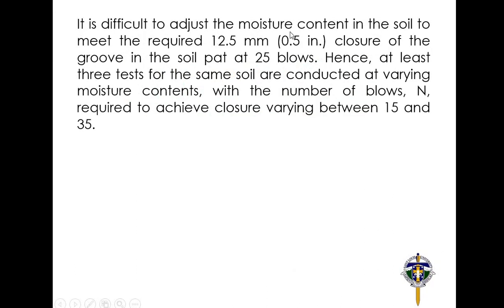It is difficult to adjust the moisture content in the soil to meet the required 12.5 millimeter closure of the groove in the soil paste at 25 blows. Hence, at least 3 tests for the same soil are conducted at varying moisture contents, with the number of blows required to achieve closure varying between 15 and 35.